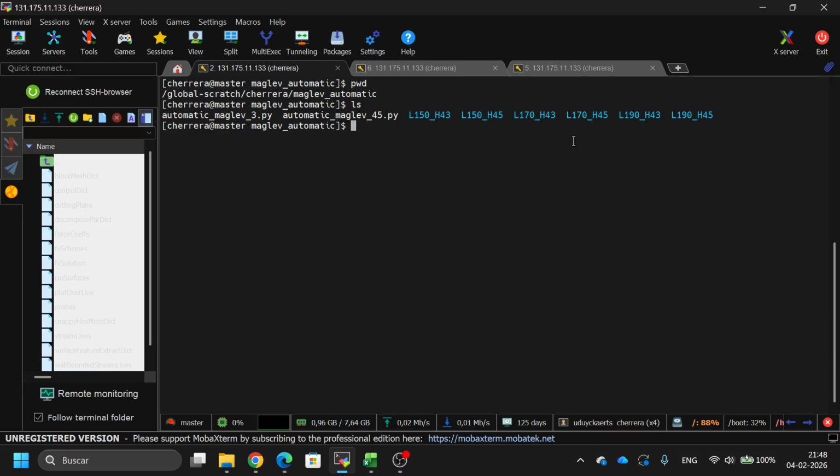That is simpler because you only need to change the constant and the system file. We are changing the length and the height of the train, so we are changing the CAD model, and to do that we need different directories with different CAD models. That's because we are using this kind of distribution for the physical parameters. Saying that, we are going to see the structure of one of these to follow for the code to work, and this is typical for OpenFOAM: system, constant, 0, and 0 origin, which is like a security copy for 0.